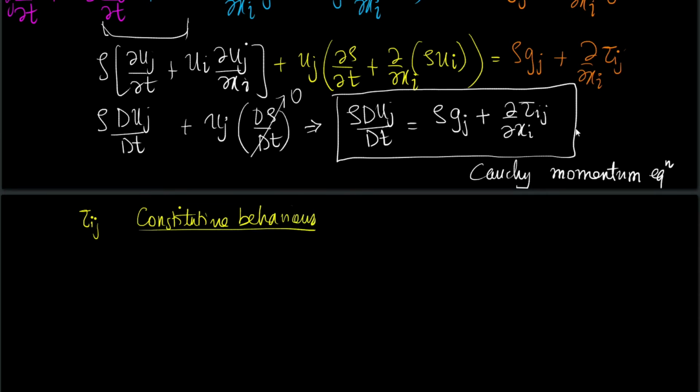This particular equation is true for any continuum. This is not just restricted to liquids, it is equally valid for solids also. But the distinction is the constitutive behavior. For solids, constitutive behavior is a relationship between stress and strain, whereas in liquids, the constitutive behavior is a relationship between stress and the rate of strain. All right.